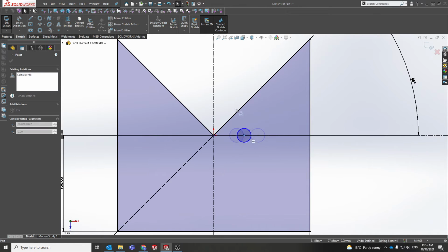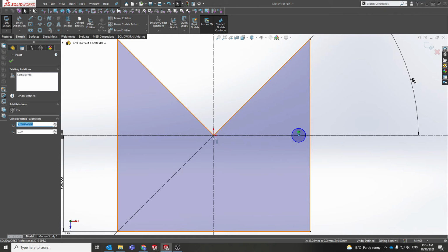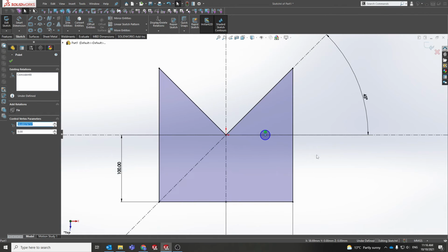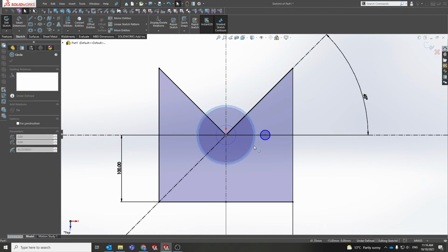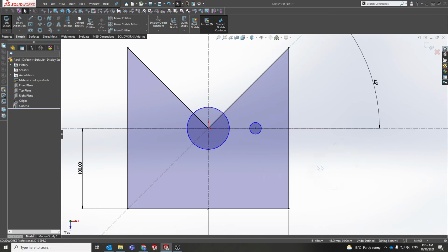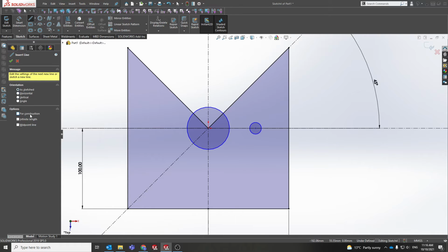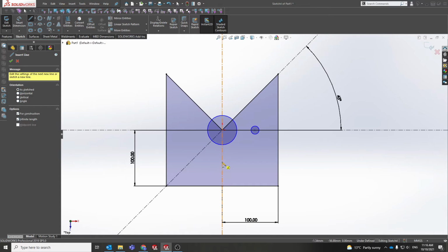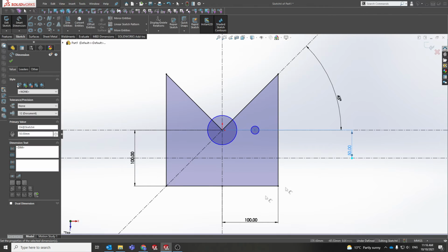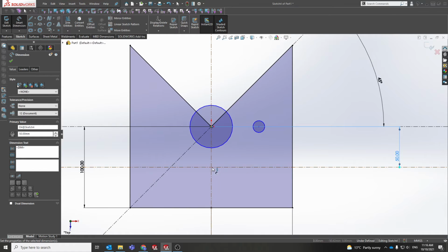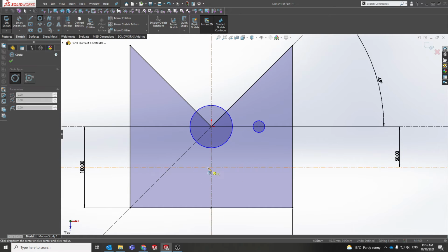So this is now snapped onto this line here, and it won't move. If I snap on this here, because it's a point, it'll have no problems whatsoever. But if I add another construction line of infinite length, I want one down here, for instance, and I define that to be this distance away, 50, and I go, oh, I want this on these two points, it doesn't actually add a point by default, so I can't quickly snap to that.